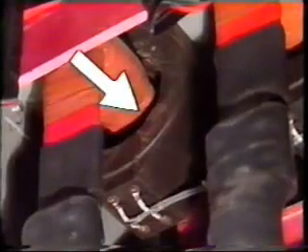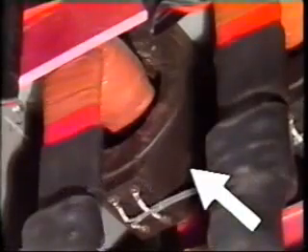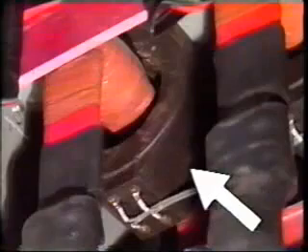This CT is called the window type. It is also known as the straight-through or donut type CT. The primary winding is the power conductor that passes through the window. Since the conductor goes straight through, it is considered to have only one primary turn. The internal winding is permanently assembled on the core to form the secondary.